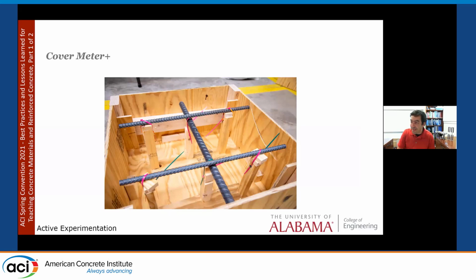Because I could just give them empty boxes and the rebar pieces and ask them to set it up some way. Now, one of the lessons I didn't put in, once you make your box and you put the lid on, you should check that the cover meter you're using can actually detect all the bars. The big bar you see here was actually lower and my device could not detect it. And I'm glad I checked before giving it to the class because they would have been really frustrated. But I like the idea. Give everyone a chance to challenge each other and find stuff. Makes it a little competitive. Can be fun.